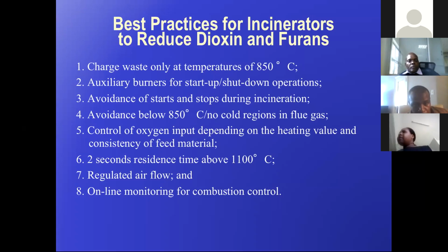And I think another key bullet here is to make sure that you have the temperature high enough before waste starts to be introduced. So it's important to prime it, to have your auxiliary burners and your fans in place, to have the temperatures high enough as you introduce the waste that you're adding to it.